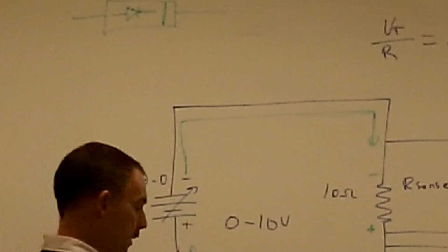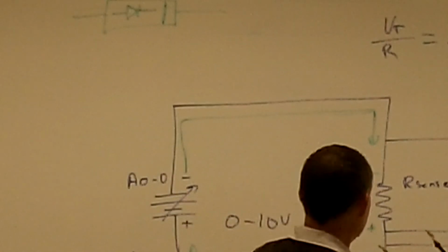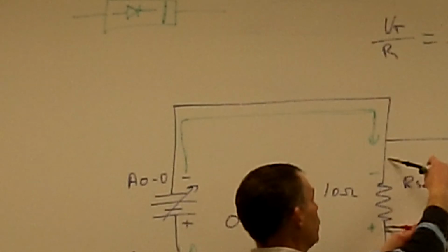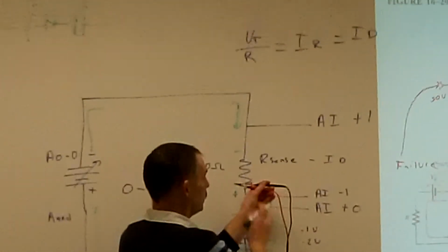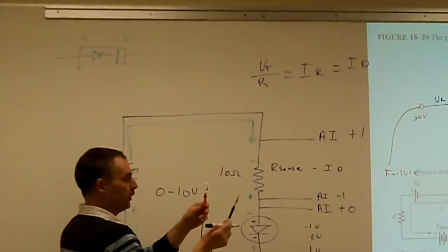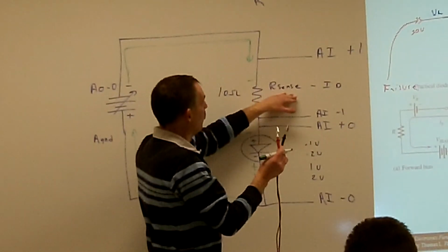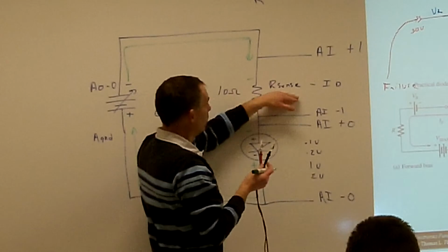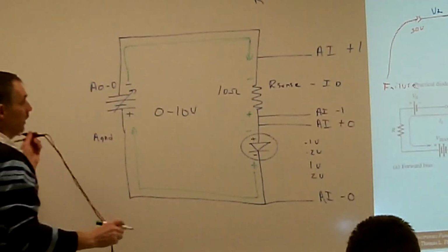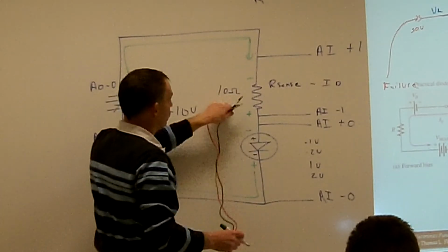So what we can do, since my ohm meter actually has an internal power supply on itself, and that's how when we're measuring a resistor, all we're doing is sending a voltage across that resistor. Then it's calculating what the current is going across that resistor, and since the meter knows how much voltage it has, and it watches what the current is, it can calculate the resistor value. So it just takes the voltage of the ohm meter and divides it by the current it measured across that resistor. It would measure a certain voltage and a certain current, and it would calculate that it's 10 ohms.